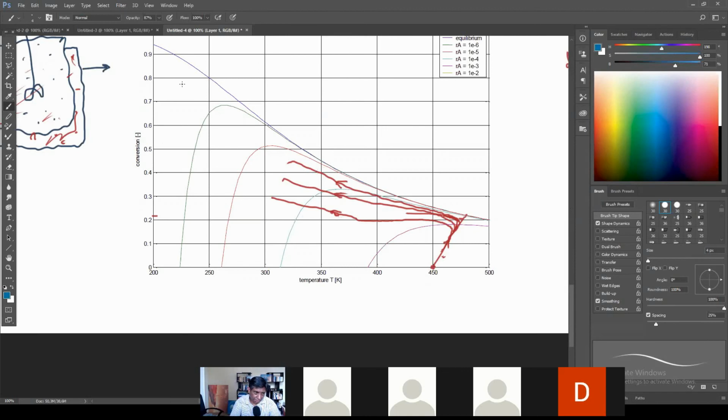So let's think about where that maximum rate path is. And of course, you've seen in the test and so on, you know how to do that. For a CSTR, you can take your adiabat and look for the points of tangency, and in a CSTR that's valid. So you would draw a maximum rate path like that. But now we are talking about a batch reactor. And in a batch reactor, the situation is quite different.